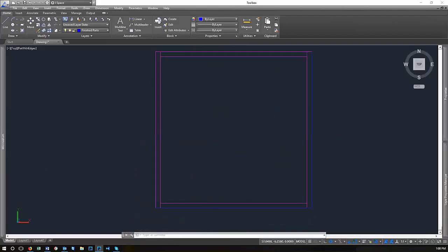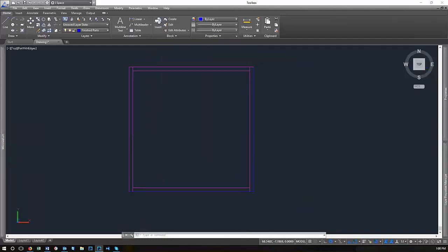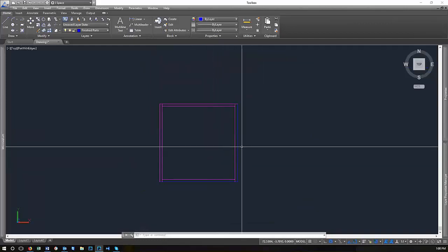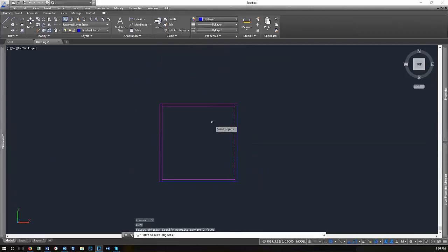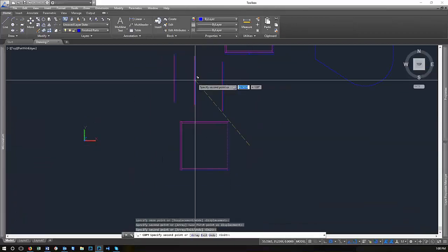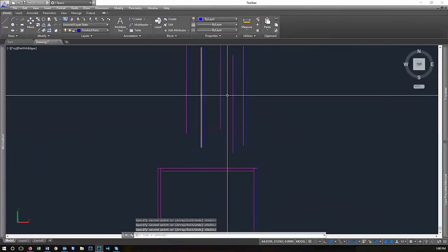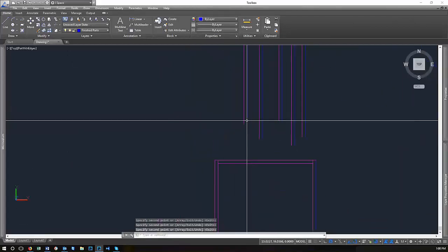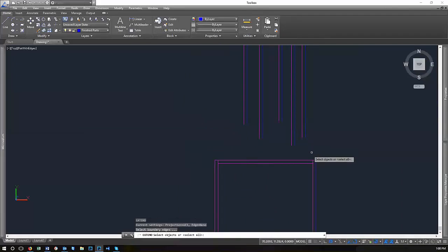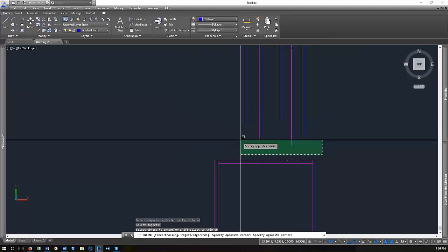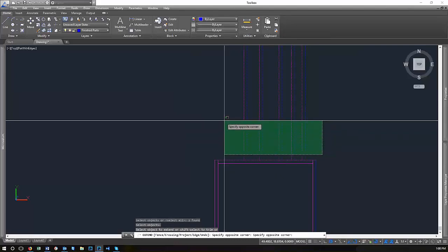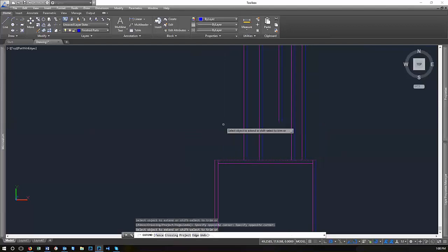So yeah, that's trim and extend, and you can select all, or you can trim all. Let me demonstrate another helpful feature. You can select all these. Okay, so now I'm going to extend, but instead of hitting each of these lines individually, I'm going to extend these to here. What you can do is use a selection, and now whenever you hit these, it's going to extend those. Whichever ones I have selected, they get extended. Whichever ones I haven't, they don't.